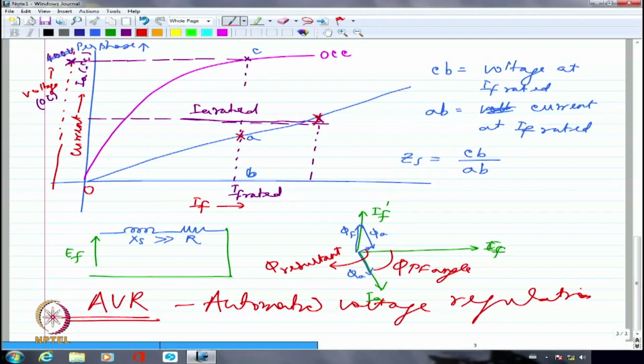Whereas here, if I try to measure the field current, that is not going to really give me an index of what is the impedance or the current that would have been drawn by my armature. They are disconnected circuits completely. And you can't even say the current carried by the armature is going to get reflected onto the field. Not at all. It absolutely depends upon what is the amount of load that you have connected. The current will only depend upon that. And to supply that load, I should have given sufficient amount of mechanical power from the prime mover. That's all it is related to.